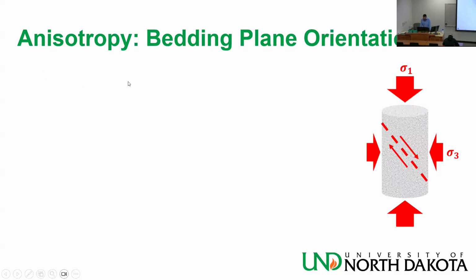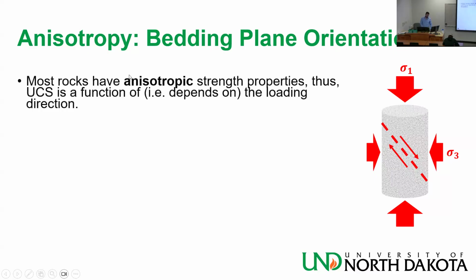This is something that is important, and we don't really talk about it. Most rocks have anisotropic stress properties. Therefore, UCS is a function of, i.e., depends on the loading direction.